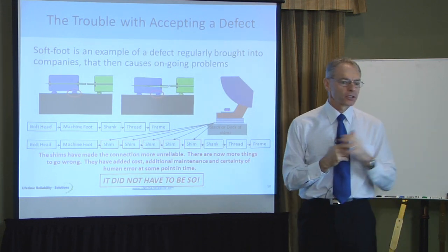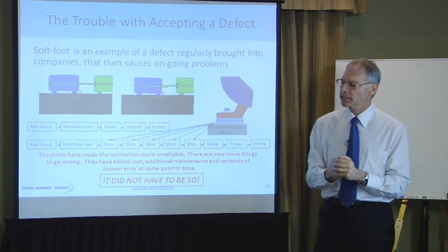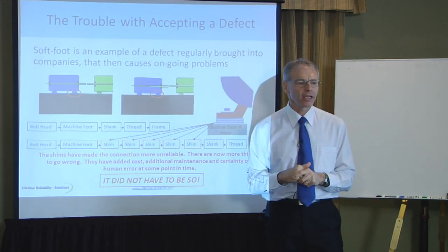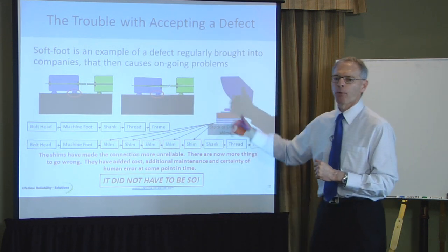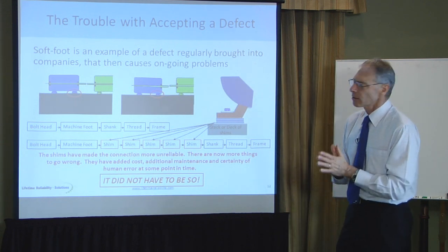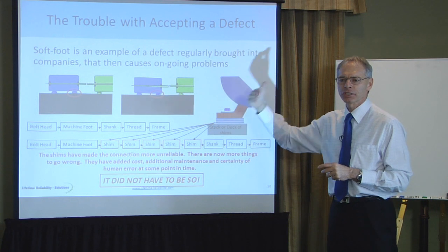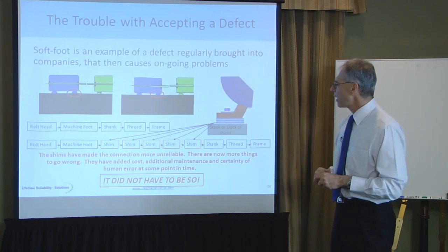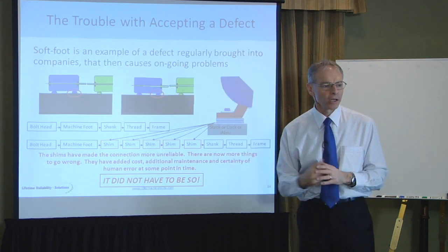That, from what the guys were telling me, is also a hard thing to get right on a regular basis. So eventually we settled on 3 as the maximum number of shims to use to not have as big a problem with slackening of faces, but it doesn't actually prevent the reliability issues in the years to come. So yes, we can solve our problems, but we don't then increase reliability. We actually decrease reliability of the equipment.